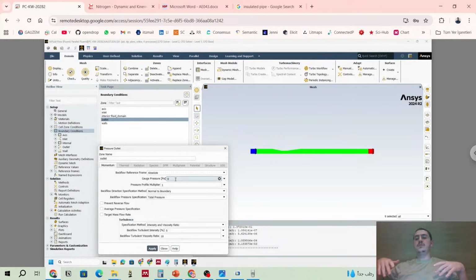So we say it's like going to reference pressure. Pressure drop will be like the outlet pressure is 0. So inlet pressure, let's say 1000 Pascal. That means pressure inlet is not given now. It's not input. Fluent will calculate the pressure inlet. Okay? We don't define it.